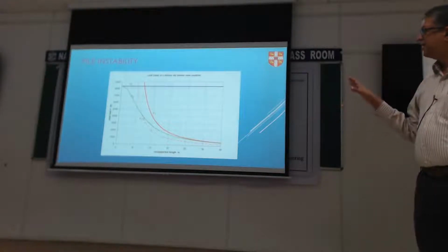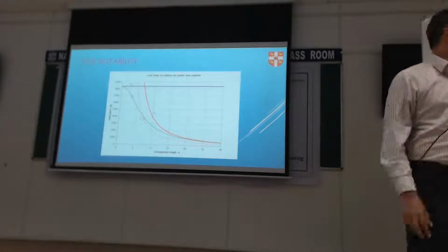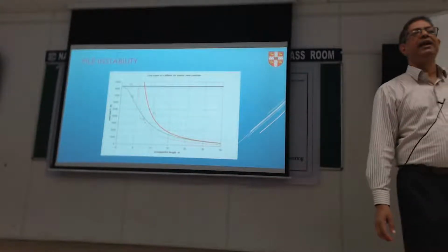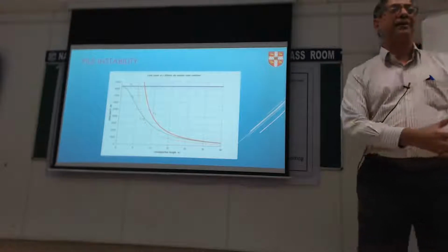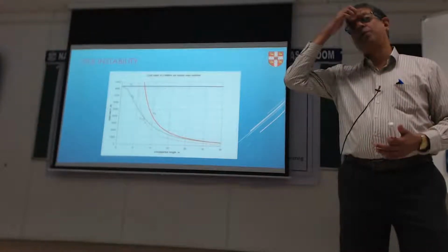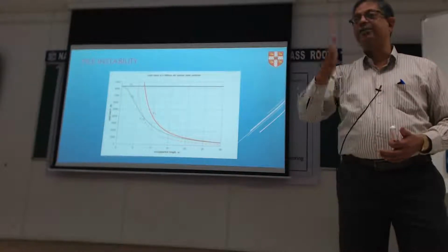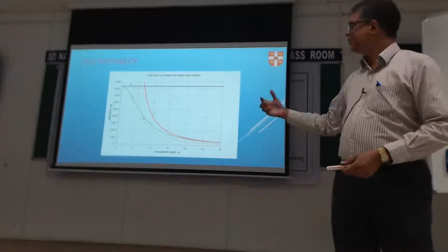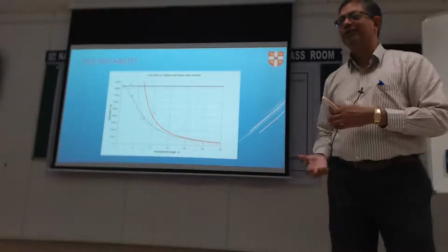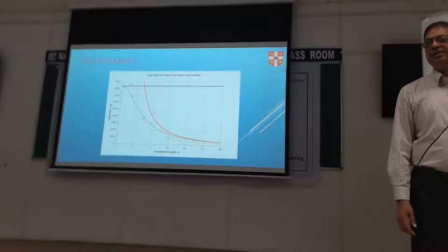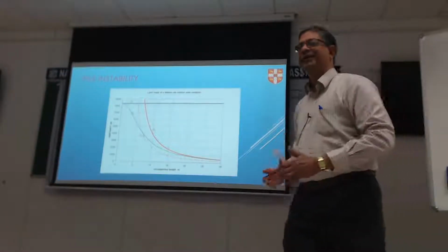So it is important to allow for these eccentricities, especially when we are dealing with applying these to piles, because we know our column loads are never so axial to the pile, and piles themselves have pile bend. So one of the ways we thought we could handle pile bend is by bringing that into E and call that the imperfection in the structure.